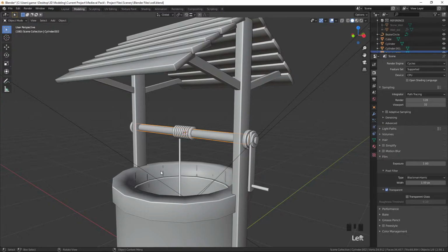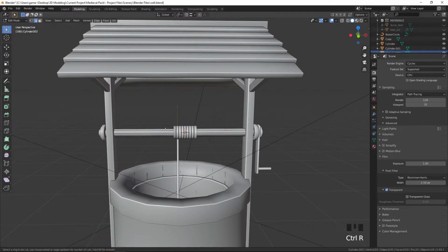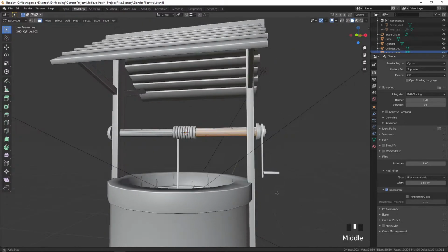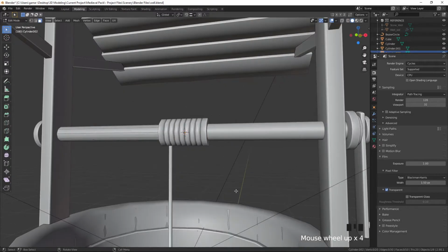And then if we click on the new object, we can go in, we can put an edge loop slap bang in the middle, press 3 for face mode, alt select across there, delete them faces.